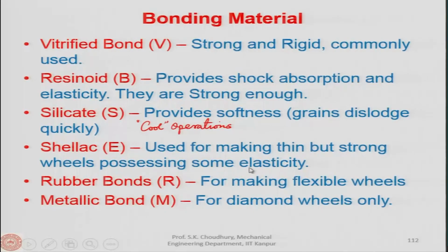In that case, of course, these kind of thin wheels have to be strong, because as you understand, since the diameter is more, as it is going inside towards the center, it can actually vibrate, and the wheel, if it is not very strong, will not withstand. It also has to possess some elasticity to withstand that vibration in case it happens in the workpiece.